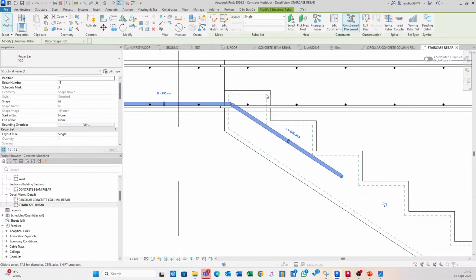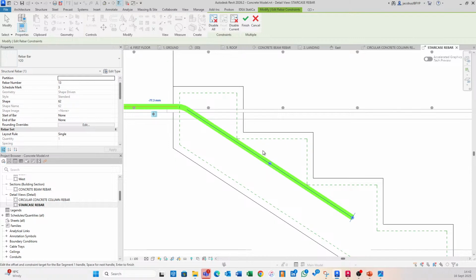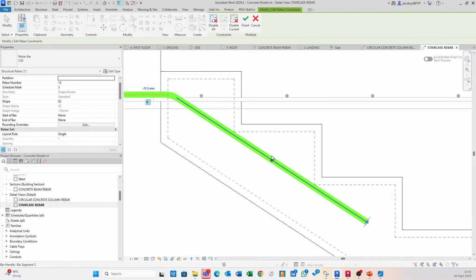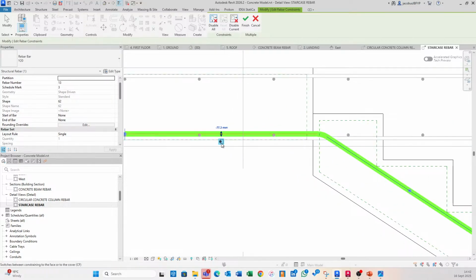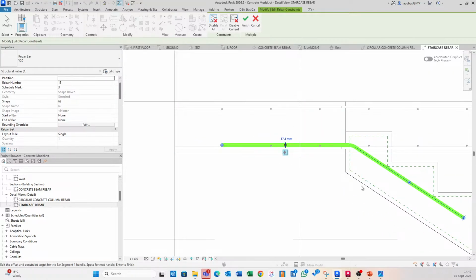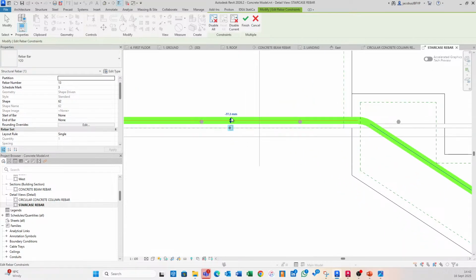Okay, but it can be that you might want to play around with that and get it really, really accurate. So you can click on Edit Constraints, and these little grips can help you with that. Now, just be mindful that if you play around with this particular grip, you're going to have problems because this is no longer seen as being in this host because, of course, we've picked a new host. So if we click on this, we might have a problem.